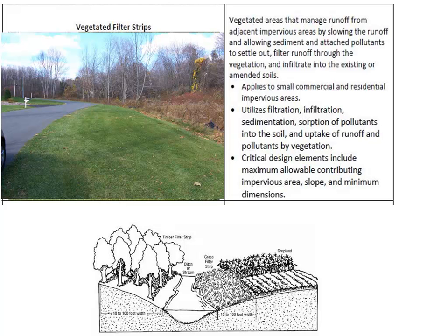Another thing is that the vegetated filter strip could be put in next to farmland, and cropland, as far as infiltration goes, is better than asphalt. It's going to allow infiltration, but if pesticides or fertilizers are applied to the cropland, having a filter strip here acts as a biological filter. So some of the nutrients like phosphorus and nitrogen could be absorbed by the grass rather than getting into the ditch. And you'll probably learn in your environmental-themed classes that excess nutrients are one of the dangerous pollutants faced by water bodies.